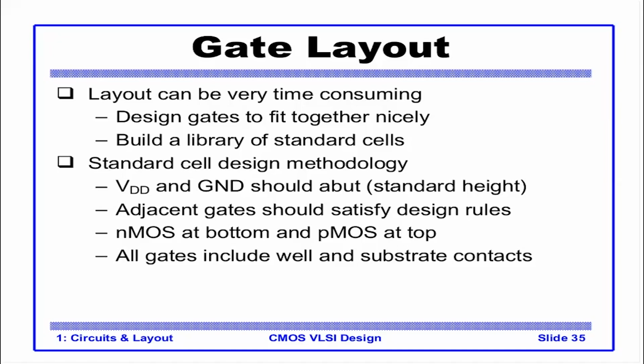Then, adjacent gates should satisfy design rules. That means that there should be some minimum spacing between adjacent gates. Always the convention is that NMOS is at the bottom and PMOS at the top. So the NMOS, the pull down network, will be connected to ground, and PMOS will be connected to VDD. So VDD would be at top.